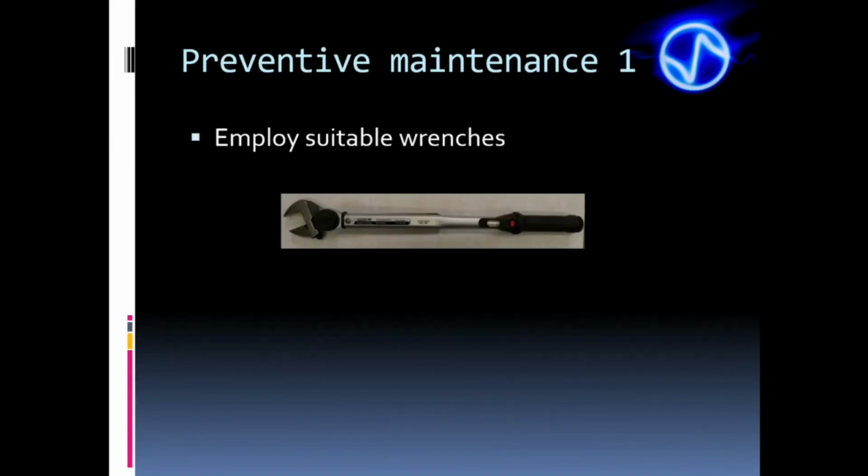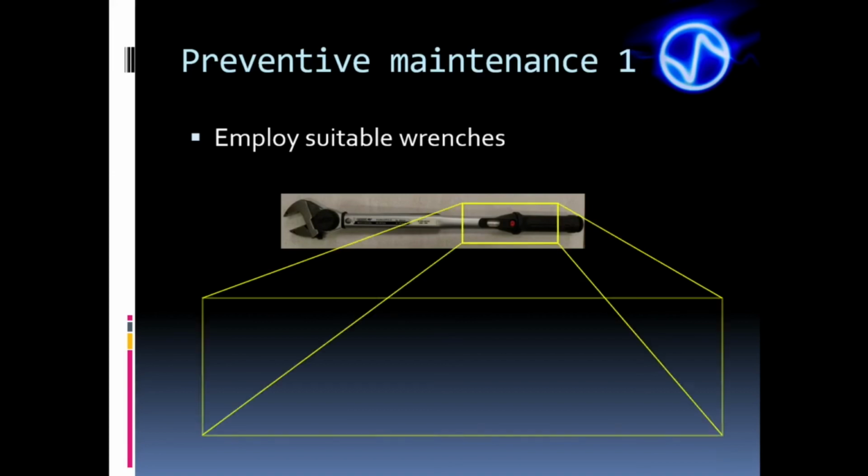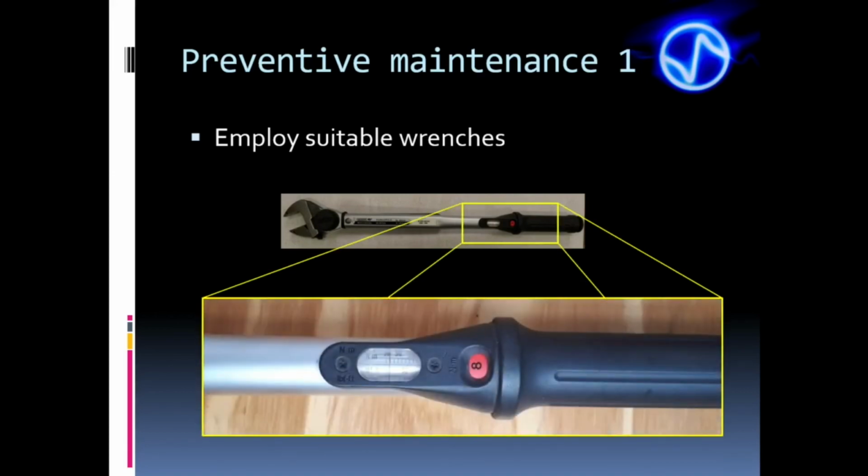This means that to assemble a 20 kHz stack using the torque wrench of the example, it's needed to set the torque wrench to 28 Nm. With this configuration, I'm going to apply the 35 Nm indicated for 20 kHz stacks.